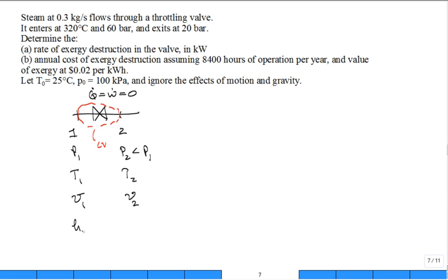And the enthalpy is the key property. What do we do when we get that out of the first law analysis around a control volume for a throttling valve? Another thing to memorize? No. Another thing to know by being able to apply the first law for that problem. It's constant enthalpy. It's isenthalpic.